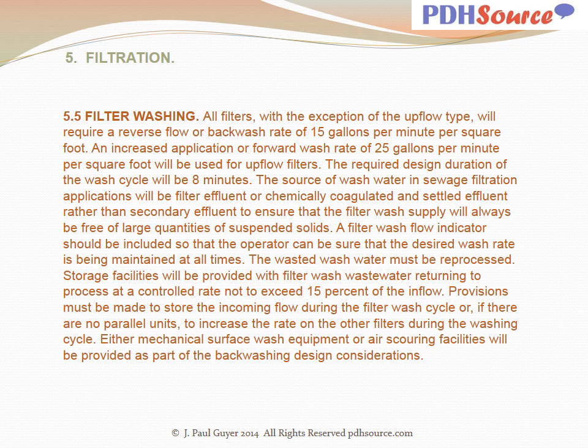All filters, with the exception of the upflow type, will require a reverse flow or backwash rate of 15 gallons per minute per square foot. An increased application or forward wash rate of 25 gallons per minute per square foot will be used for upflow filters. The required design duration of the wash cycle will be 8 minutes.